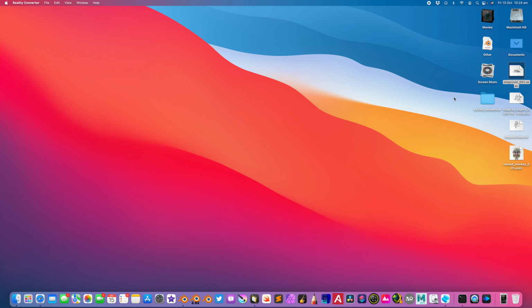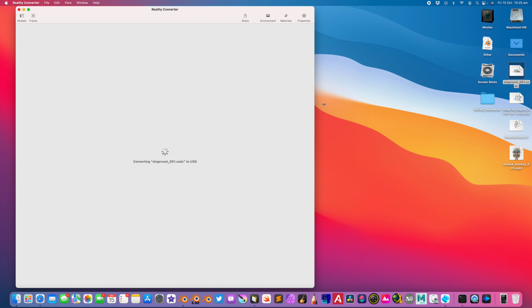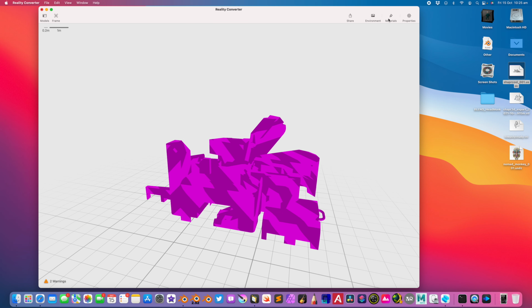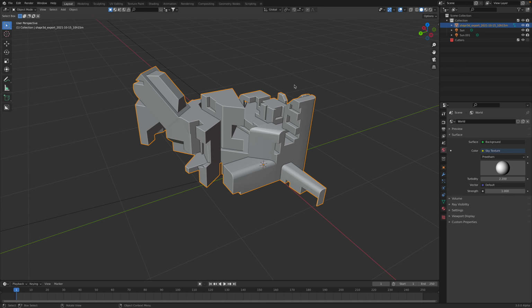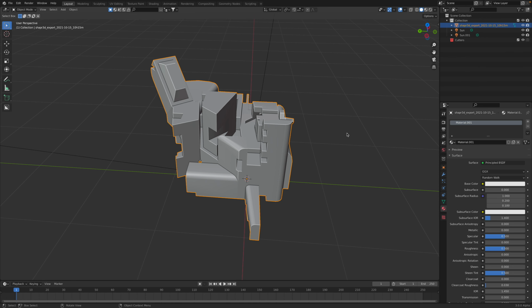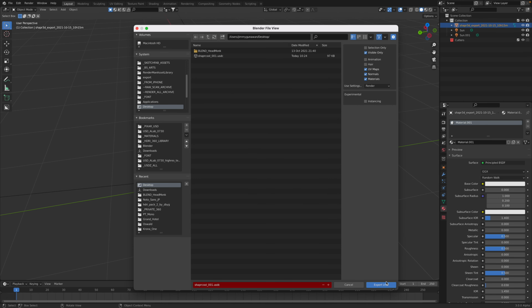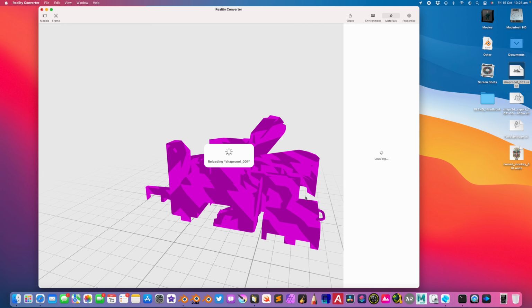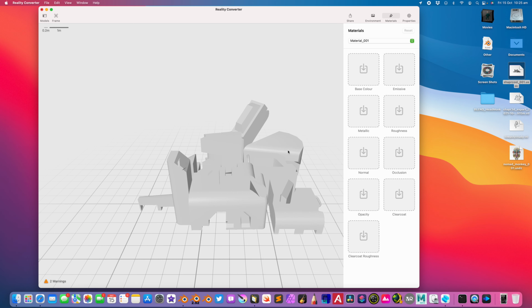Okay, let's use USD because you can easily look at it and something that you can export as AR. So it's Shapr3D to do some CAD modeling. It's actually a pretty real app, you know. Okay, it's missing material. With USDZ, if you want to export properly, you need to have at least one material. File, export again, USD, export. This doesn't always refresh. Let's do that again.